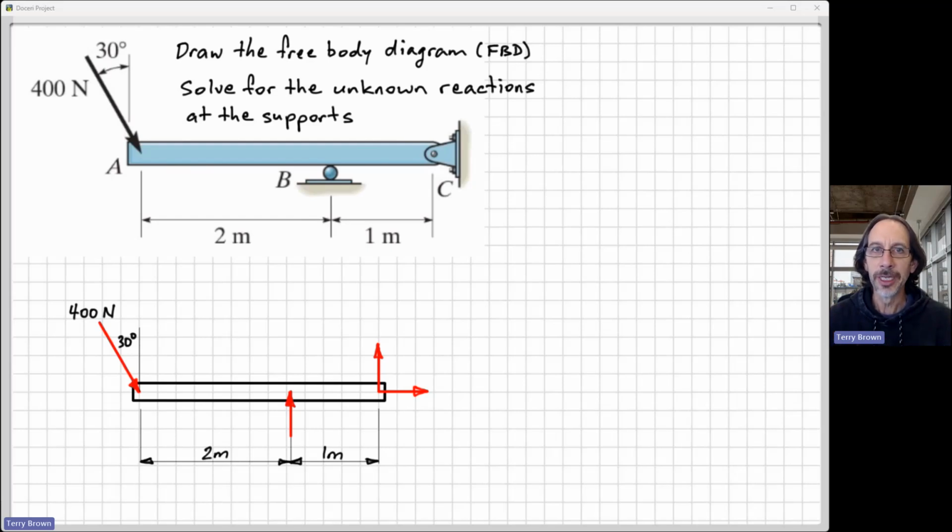You would have seen in lectures and videos on modelling the supports in rigid body equilibrium problems, there's a table of about, I don't know, a dozen, 12 or 15, something like that. Students look at that and think, oh, do I have to remember all of those? Well, these days you've got usually open book exams and you can look things up. But if you don't want to have to go back and look it up and just remember how to do it, you do it by thinking about, as we've just done, what motion is free and what motion is constrained.